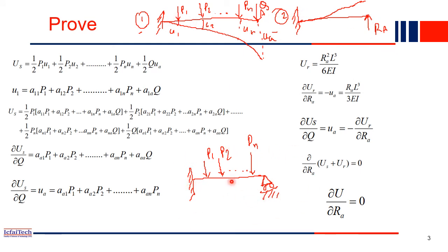So if you see in the real beam at this point A, what is the displacement? When we divided, there was no support, so deflection is allowed here. Here also we applied only the redundant force, so deflection is there. But in the real beam at this point, what is the deflection? It is zero, right? Because the support is there, whatever loads are acting. If you draw the bending diagram, the displacement at this point A is zero, because here we have support.